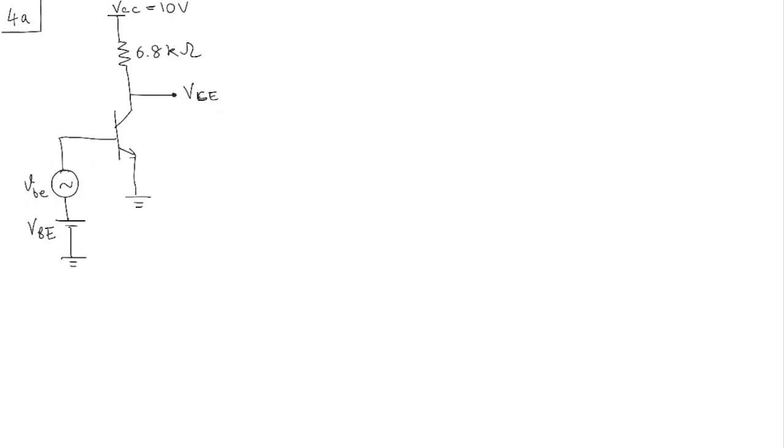And you can see that in this question, it's not very easy to solve the problem because we're asking for VCE, and for that particular VCE, we are not able to calculate any currents here, right? We can calculate VB because this is 0, so this can be 0.7, but we can't really calculate the emitter and the base currents. So what we would have to use is what is called the exponential model